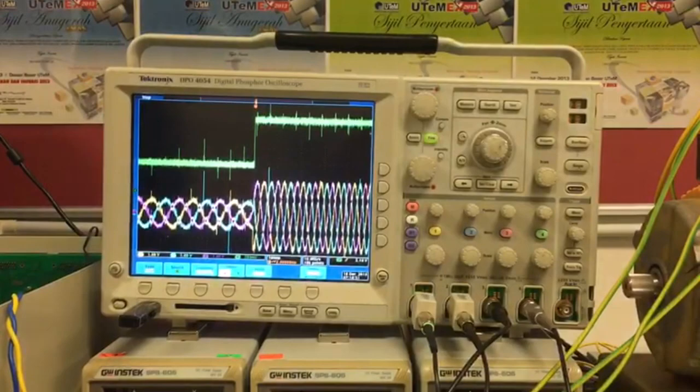Initially, the torque of the induction motor is set to 1 Newton meter, and the three-phase current has lower amplitude. When it is suddenly increased to 3 Newton meters, we can observe that the frequency of the current cycle increases. Other than that, the amplitude of the current also increases. As a result, the induction motor has higher rotating speed.